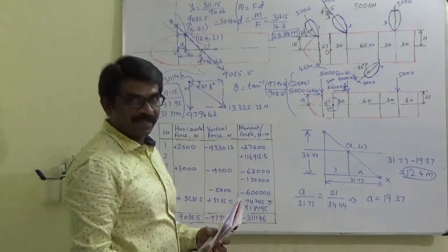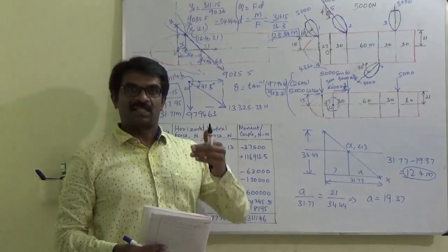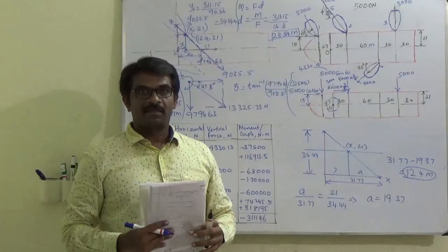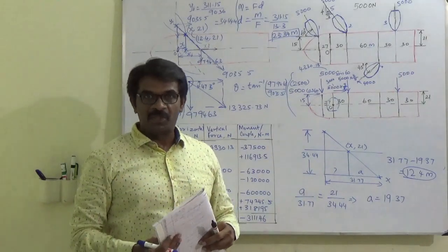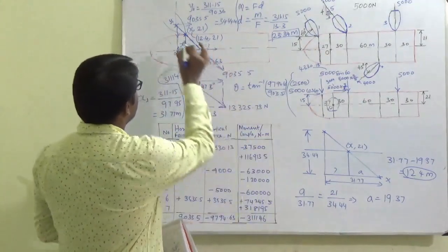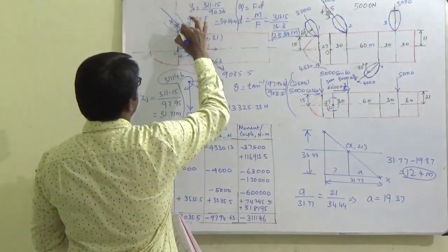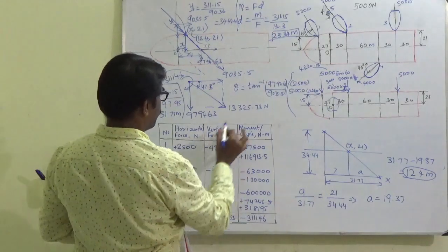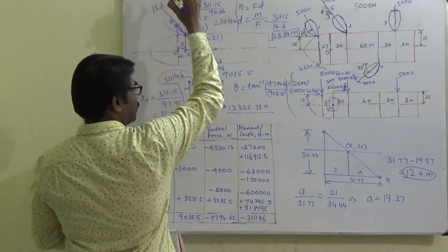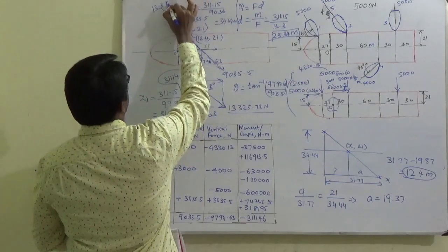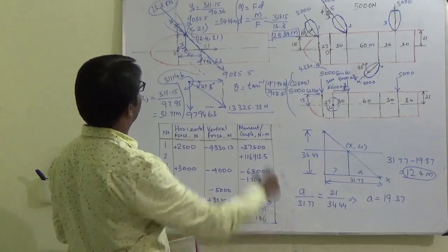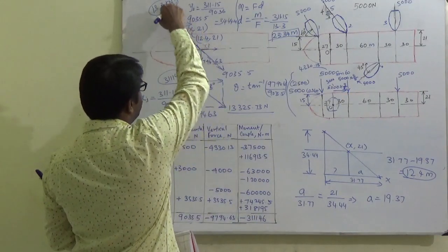We have found that. So from the foremast point, if the single bigger tugboat is used, what is the resultant force that is acting there? The resultant force will be 13.33 kilonewton. So 13.3 kilonewton force is acting, okay, in this line of action.